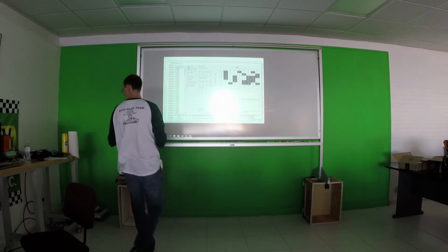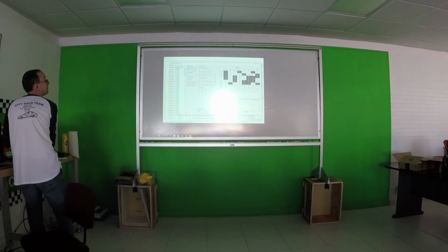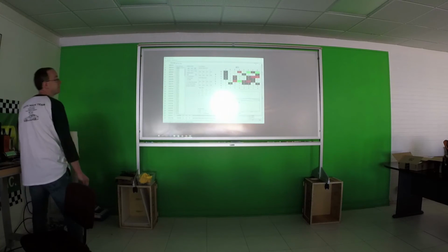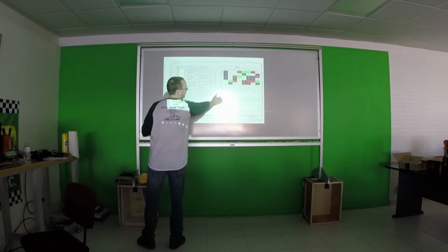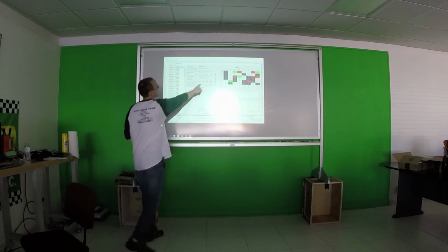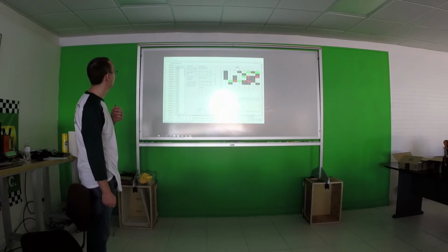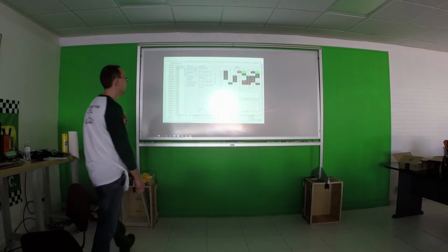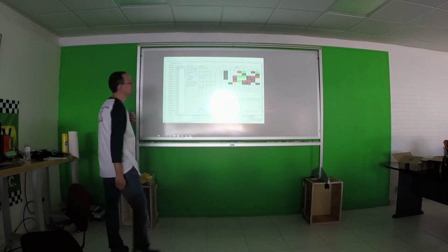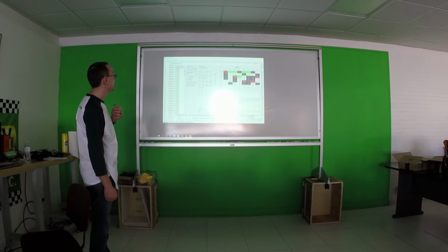Now, this has the same type of playback controls, the playback window, where the green arrows are single step, stop, pause, play backwards, play forwards. So let's say I'll slow this down because it's hard to see otherwise. If I go at 205 playback speed and start playing this back, these are graphs of all of the data bytes. And you can see they're updating here for their current values. This allows you to see what the data bytes are doing on this ID as time goes on. The time axis is in seconds. So you can see how quickly all those bytes are changing as seconds go by.